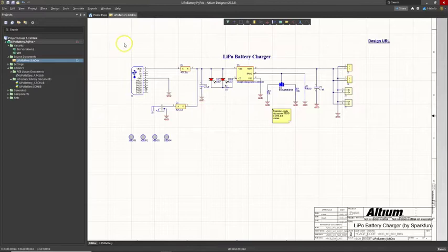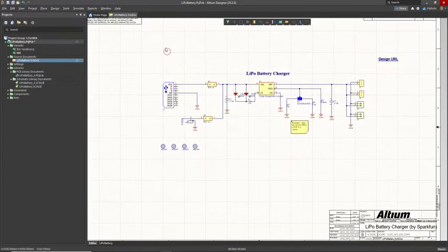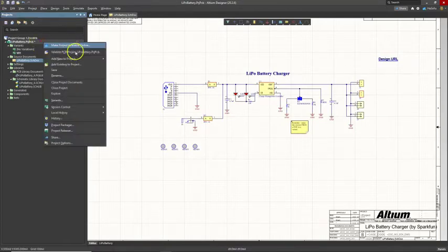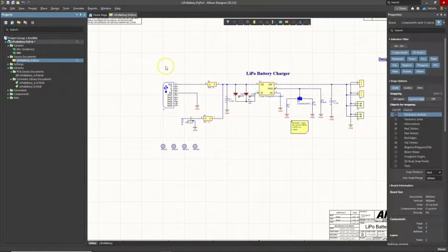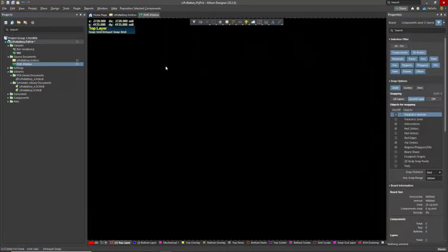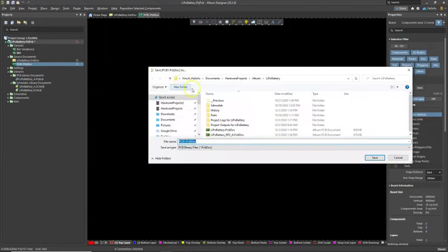Once you're satisfied that your schematic and parts have all the information you need, let's create a PCB document. So go to your project, right-click on it, and then choose Add New to Project, PCB. This PCB project document gets added automatically, and see how it goes underneath the schematic? There we go. You may have a PCB project document already, and that's fine. Now what I do is right-click and save, or save however you do it.